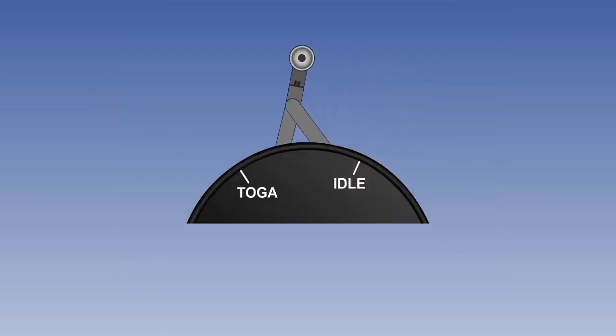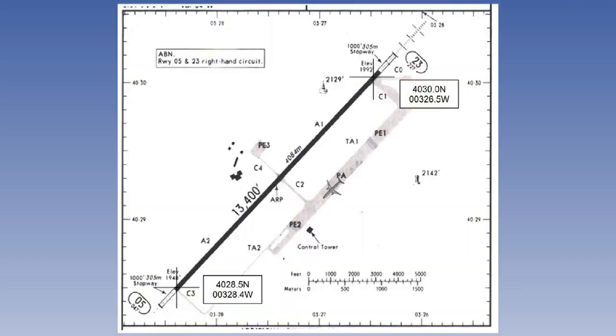As the takeoff roll is commenced, the throttles are advanced. A contact on the throttle quadrant is called the takeoff go-around switch, or TOGA switch for short. Operation of the switch automatically updates the FMC position to the takeoff threshold. It is also possible to input a displaced threshold. Suppose that we do not need to use the whole runway length and have decided to take off from 2,300 feet past the threshold. In this case, the pilot inputs a correction factor for the displacement distance, and a new position is automatically calculated by the computer as part of the update.